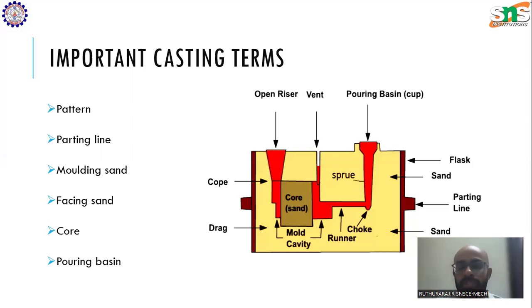does not melt during the pouring of molten metal, and it can easily be removed once the metal is solidified. Sand has such excellent properties. So we will make the core using sand with some binders. Sand is made into a solid object and it is placed inside the mold cavity, which is called core. Once the metal solidifies, core can be easily broken away and you can get a cavity inside the casting. Hollow object can be made. So that's the purpose of core.